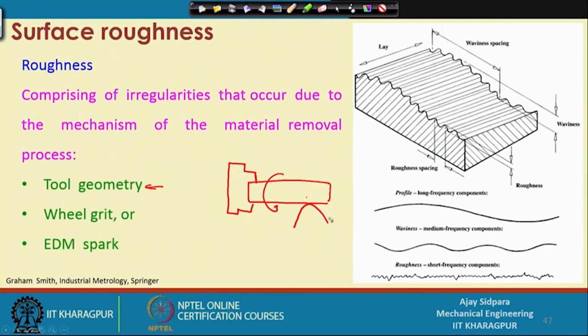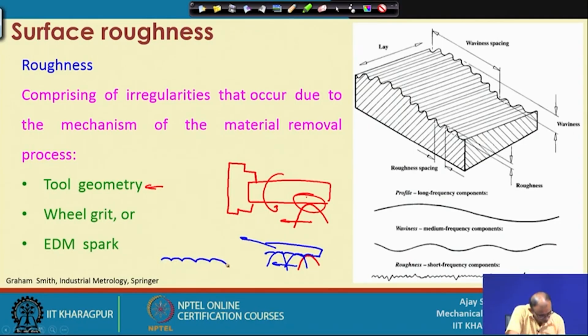We are rotating it in this direction. So, if you zoom in on this particular area, what is going to happen is that we are moving the tool in this direction, and we are rotating the workpiece in this anti-clockwise direction. Your tool is actually penetrating inside, and this is your workpiece. Right. So, these are the different conditions or locations of the tool with respect to time. It is going inside and inside. So, once you complete this machining, what are you getting? You are getting small artifacts, the impression of the nose radius.